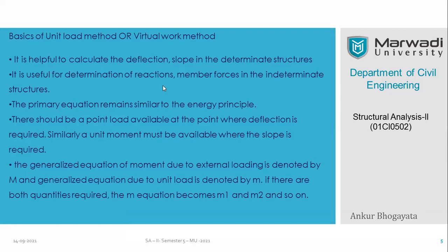However, looking at the scope of our study right now, we are restricting ourselves to determinate structures, but in future definitely you can use it for indeterminate structures and calculate reactions first instead of the direct slope and deflection. You can first obtain the reactions, and based on that, you can definitely get the internal forces also. So the primary equation remains similar to the energy principle, that is EI d square y upon dx square equals minus capital M.